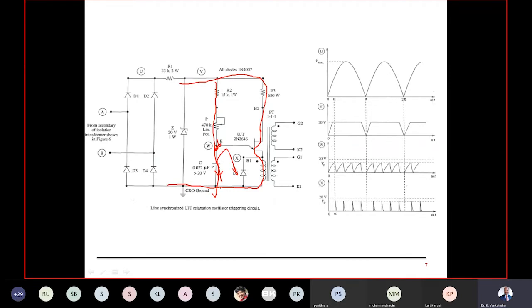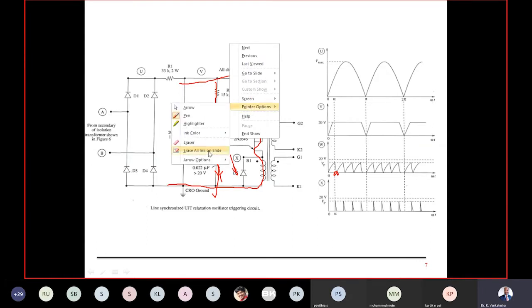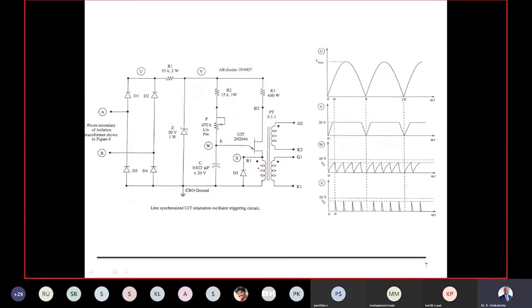Then, once my capacitor voltage reaches a value somewhere here, the switch will be turned off. When the switch is turned off, whatever energy is available in the inductor will freewheel in this manner, and the power is dissipated in the primary winding, which has both resistance and reactance, which is not shown here. Every coil has resistance. The power will be dissipated in the resistance of the coil itself. Again, it will energize freshly when the capacitor voltage reaches peak voltage during the second cycle.